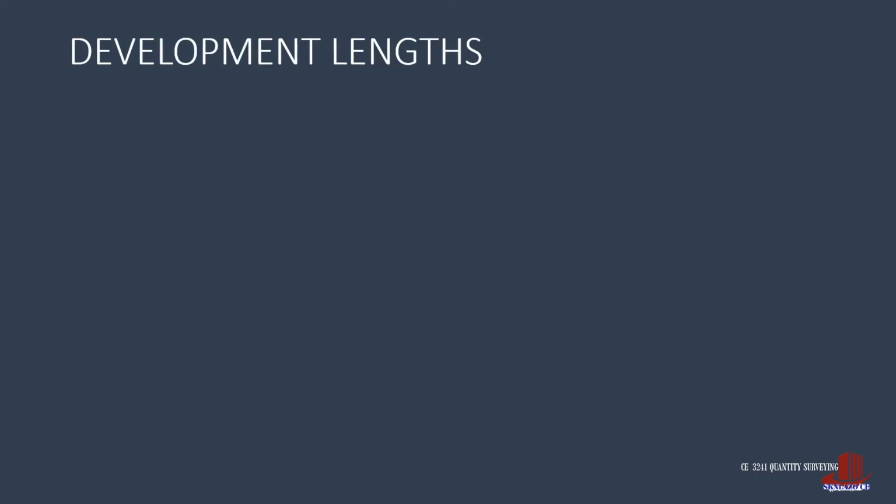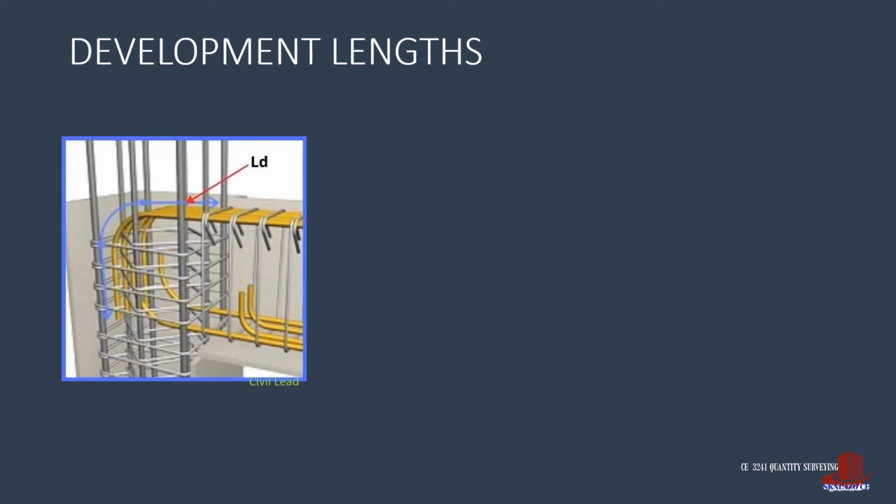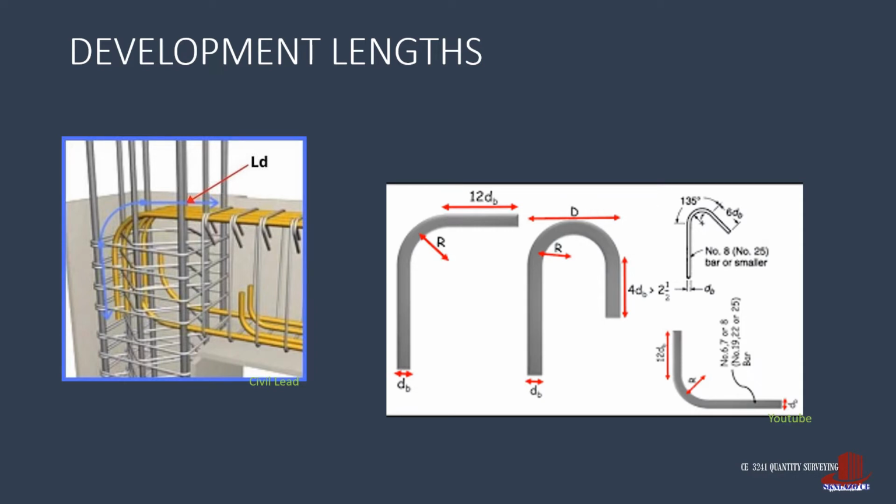Besides computing the required length of rebars per member, there are still additional lengths which we can categorize as development lengths. Such are from the bends or hooks used depending on the member. Commonly, the bigger diameter bars would use bends as it would be more difficult to create hooks from them. And needless to say, with the same reason, the smaller diameter bars can be fabricated with hooks.